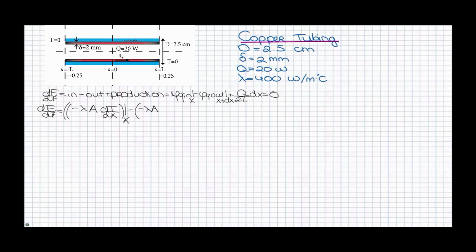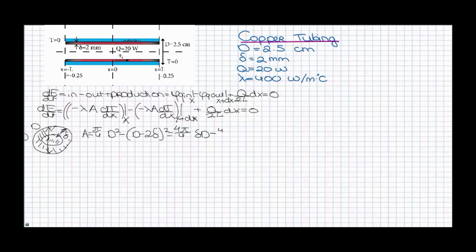We can now rewrite the heat fluxes with Fourier's law. A is the surface where the heat flux is transported to, and that is not a flat plate, but it's now a tube. So we need to observe this surface of the tube, because there is the heat flowing through. And we know that the whole tube has a diameter of d and the layer thickness is delta. So the surface is described as follows, and if you write this out you will find this equation.